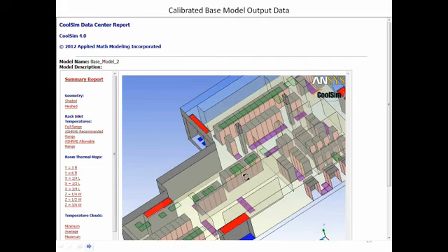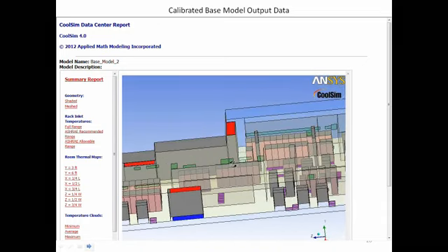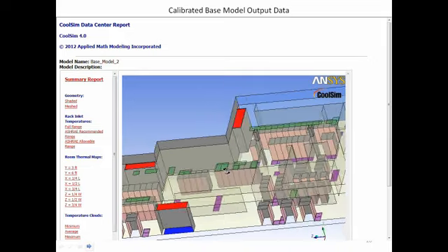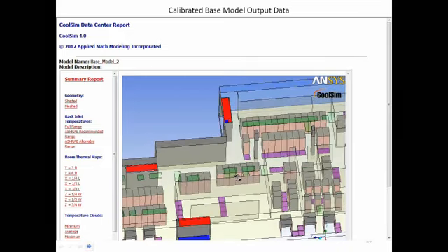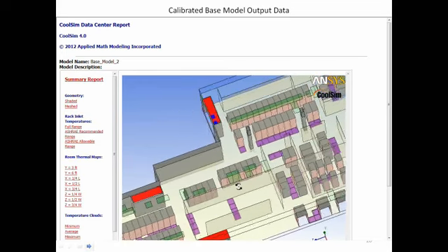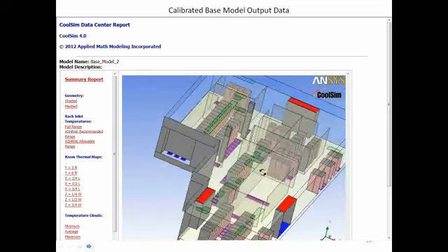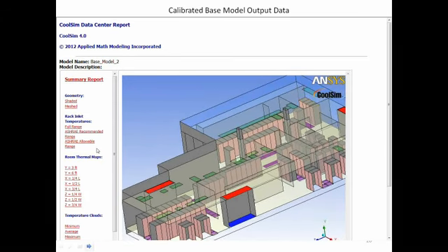Right. But you can see here that this does have a ceiling plenum. That's a good thing. So we do have air coming back to the cooling units via the ceiling plenum. That's nice. I like that. But it's basically naturally convective back. It's not being channeled in any way. There's no baffling going on. There's no containment going on. It's just coming back through the ceiling plenum.